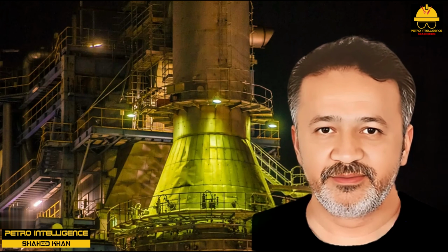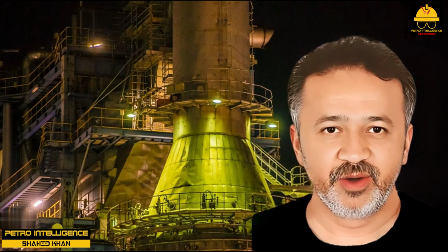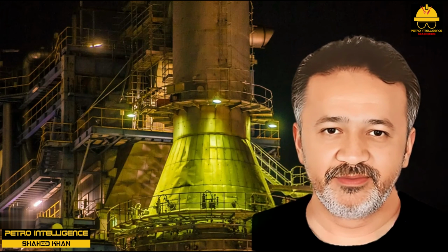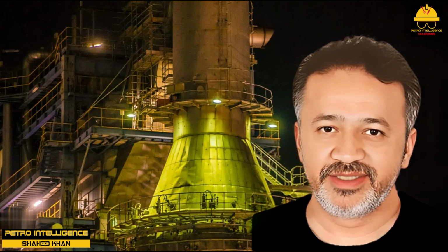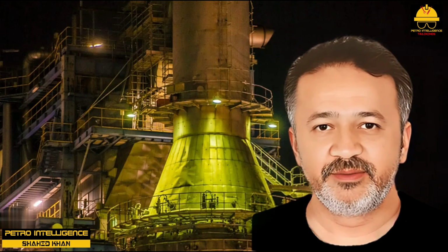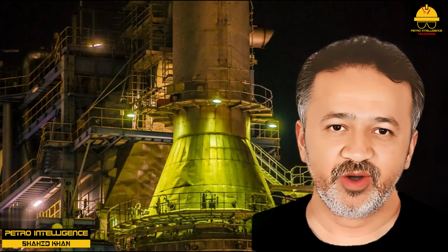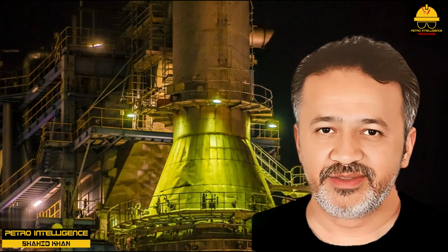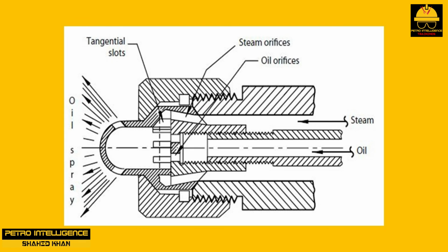Oil burners. In the United States, oil firing is uncommon. In Europe, it's pretty standard. Most oil-fired burners use atomizing steam to produce a large surface area of the oil exposed to the combustion air. In the steam atomizers shown in the picture, jets of oil under pressure meet the spinning jets of steam under pressure in the mixing chamber. A mist of oil and steam is discharged into the furnace.